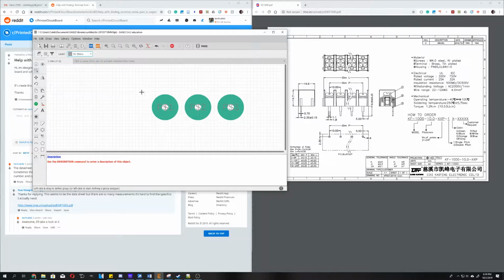If you want to actually put your own alignment marks, then you can put those on other layers, like tPlace, for example, is where you would actually put like a little angle bracket if you wanted to have a place to show exactly where to line up the parts. But this should be fine.